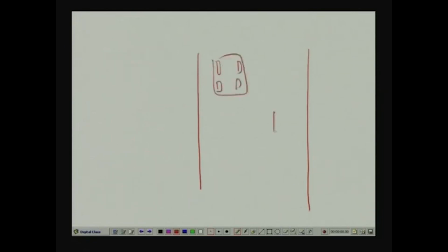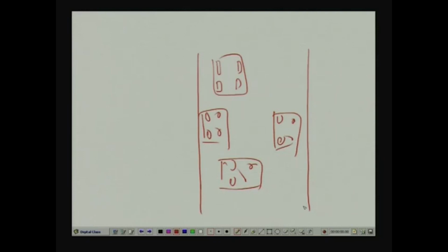For example, what we are trying to indicate is, if this is the pavement, at a given point of time, if this is how the vehicles are placed, if we put these wheels in exactly the same position, if this is a realistic practical positioning of vehicles, then depending on the traffic intensity and the facility that is available, all the wheels are not going to travel along the same path.